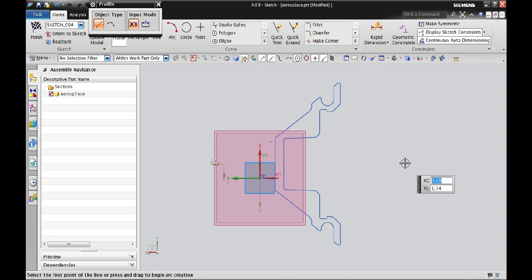We'll do all the front operations on the main spindle, all this one all in the main spindle, and all this one in the back spindle. Again, it's an example part. Depending on custom operations, we'll go and depend on the user preference going forward. Whatever type of part they want to see turned, we'll do it.